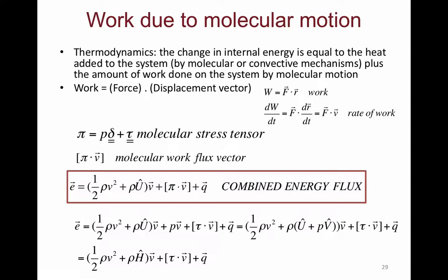So now we have the velocity as given. We're going to just use this solution. Okay? And we have this temperature difference between the fluid. But there is also this extra friction part. I have very small slits, so the viscous heating is somewhat disproportionate because the layers and surfaces are really close. So instead of what I would expect as a linear temperature profile, it's not going to be linear. There will be an addition due to heat generation within the system.